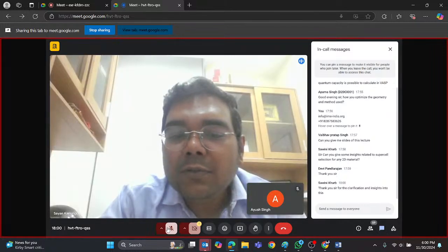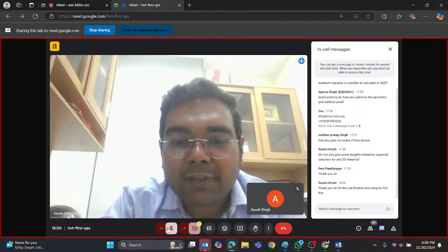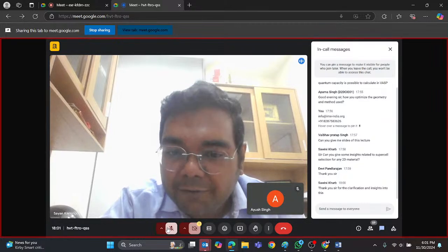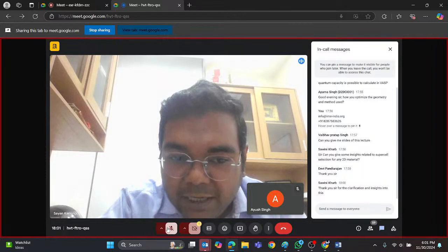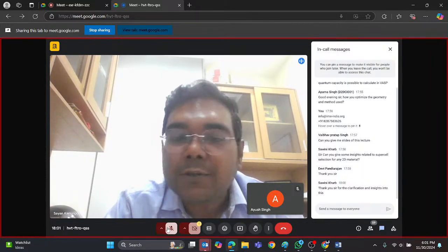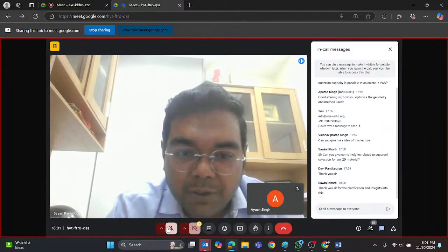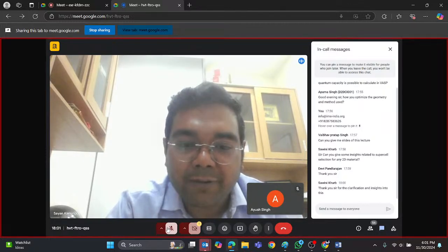I think you can use the NEGF transport tool of Quantum ATK to have the ballistic IV characteristics under the ballistic regime of operation. But if you wanted to look into the mesoscopic transport, that would be difficult to directly get from Quantum ATK. You might have to integrate your material property under DFT Hamiltonian into some mesoscopic carrier transport framework. Maybe you can look into some of those open source tools which are available, which offer you this Boltzmann transport equation framework where you can fit in your material Hamiltonian, and you can calculate the IV characteristics.